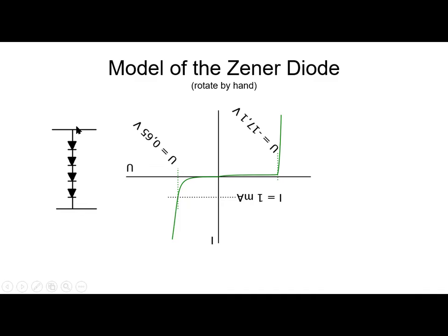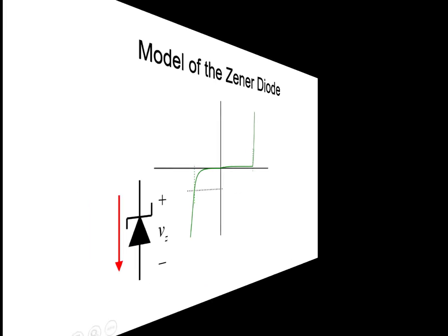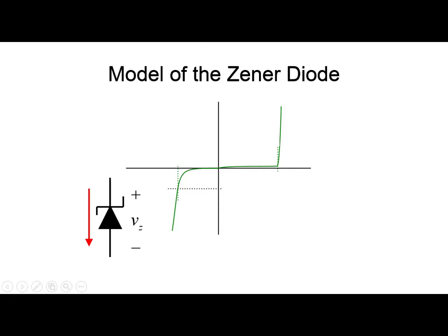Now, instead of using, for instance, 4 rectifying diodes in series to achieve a voltage of 2.8 volts, now we specify a Zener diode connected between the same 2 points backwards, like so. That would be a 2.8 volt Zener. Before proceeding, let's label the axis we're going to be working on. Formerly, this one down here used to be the positive direction for the currents in the rectifying diode. We will not be there. And this one on the left used to be the positive voltage drops in the rectifying diode. We will not be there either.